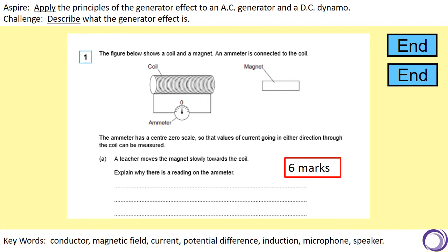If you understand how an ammeter like that works, it uses the same principle. It's got a tiny coil on it attached to the needle, so the coil is effectively moved by the current that's flowing through it in the magnetic field. So it works in the same way.